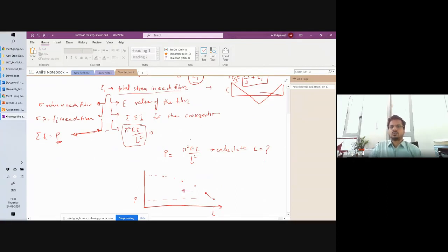Let's say you should have at least something like 20 to 30 data points from your smallest epsilon 1 to the final value. You should have at least 20 to 30 data points or more. And also you should do fine enough meshing.